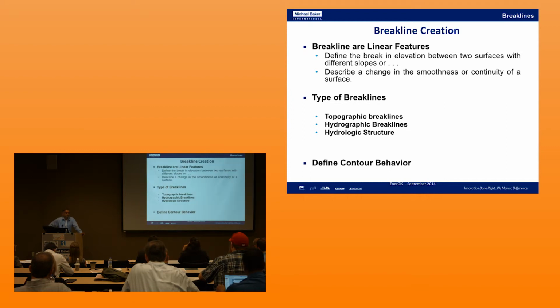So ultimately, as I said, one of the derivative products that you can get from LiDAR is a contour, and the contour should follow the terrain as closely as possible. So to that extent, breaklines play an important role in creating the final products from the LiDAR data.